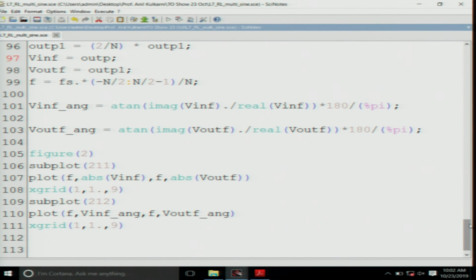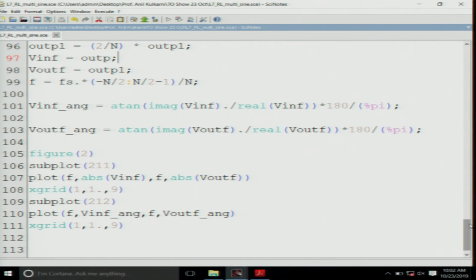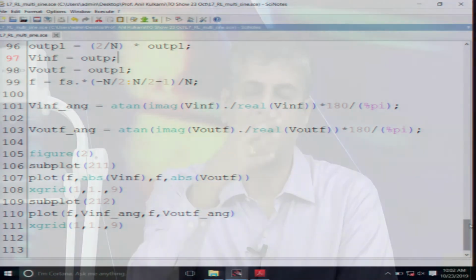Okay. Now, this is over a large number of samples, because we have taken h equal to 10 microseconds. So, it is a really large number of samples. Such a large number of samples is probably not required if you have waveforms of 10 hertz, 100 hertz, 25 hertz and 40 hertz, and time constants which are only 0.1 seconds or 0.01 seconds. But we have probably been a bit inefficient by considering such a small integration time step. So, we have got a lot of samples. In fact, we can downsample it, because the responses do not contain very high frequency components.